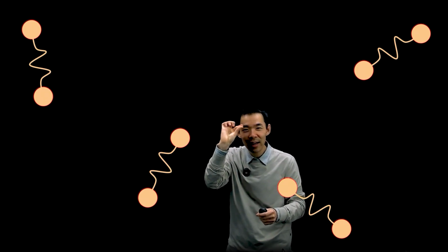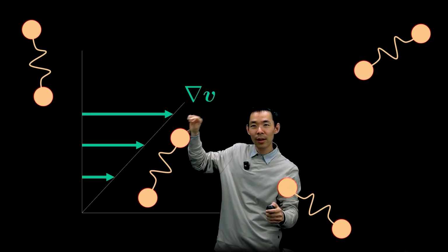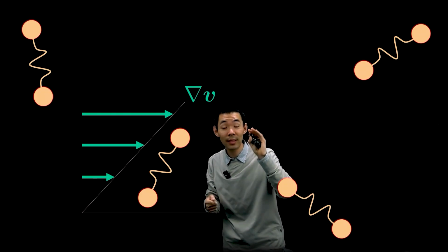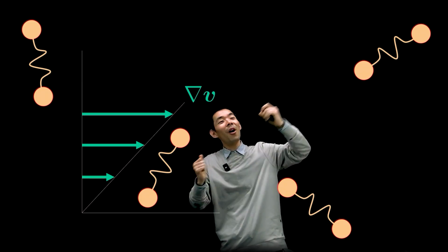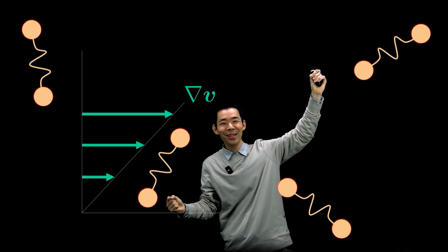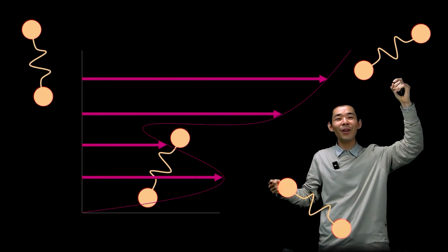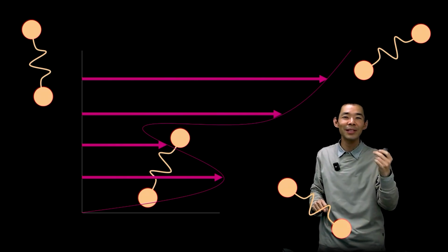Also, most constitutive equations assume that the chains are very, very tiny and short and small. So even if you have a crazy flow happening, locally, if those chains are experiencing a linear velocity gradient, then that's okay. That's the underlying assumption present in almost every constitutive equation. But if you have long chains, like the worm-like micelles I just showed you, it may actually experience two very different parts of a velocity profile that may cause a breakdown of the constitutive equation assumptions that are built into those models.